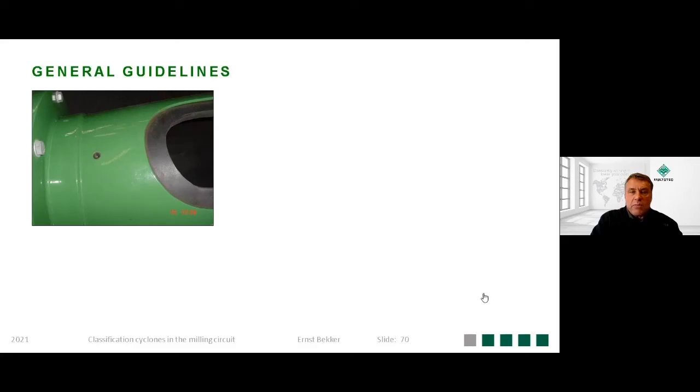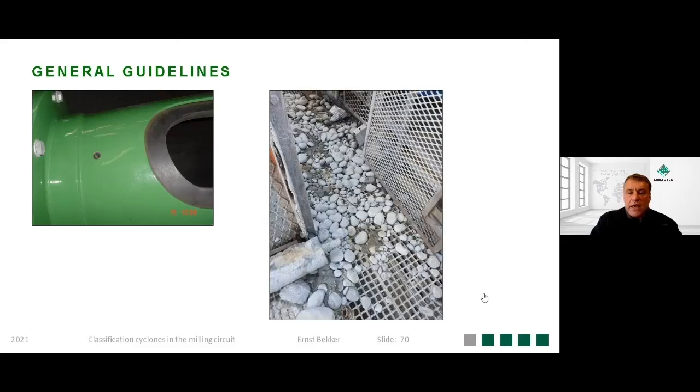And then lastly, we've talked about the trommel screen and the importance of having a trommel screen. The photo that I'm showing you now on the screen, gentlemen, I kid you not, came from the cyclone overflow. That is material that got discharged through the cyclone overflow. Now, before you think that maybe I'm losing it, the cyclone got blocked because I removed the trommel screens and that material started to discharge through the overflow. So if ever you think the cyclone cannot discharge coarse material in the overflow, this is the first time I've seen that. I just put it up for interesting purposes.